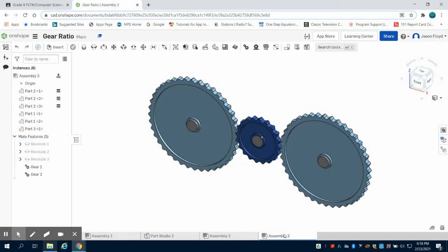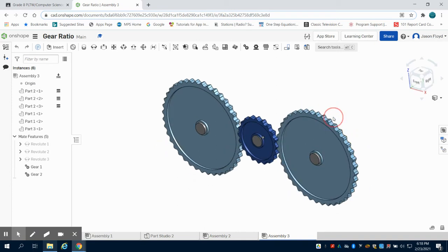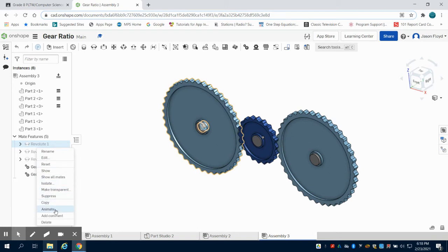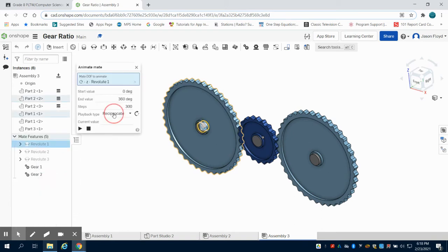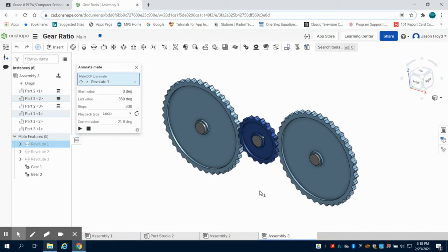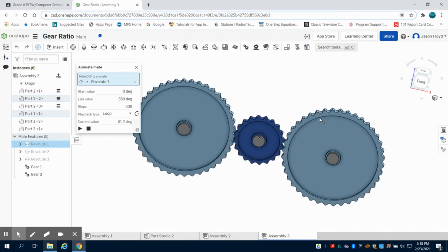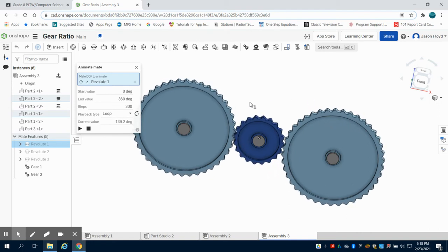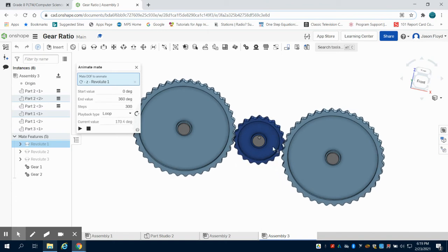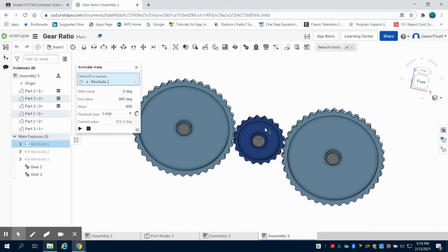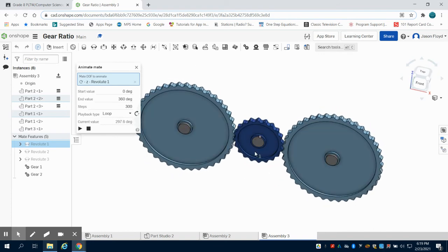And then ultimately we'll show how to put the 3 gears together in a simple gear train with an idler, where you can see in this example the drive gear, which is this first gear, spinning counterclockwise at the same rate as the driven gear here. So they're traveling the same speed counterclockwise, but we have that idler in the middle with that gear relationship spinning clockwise at twice the speed of the outside gears.